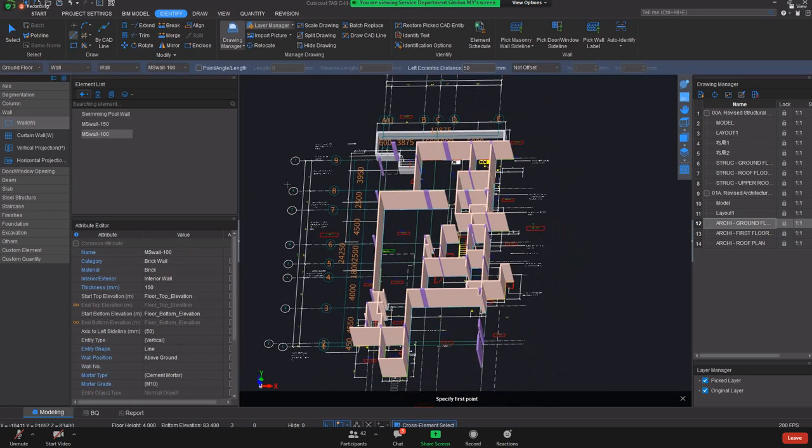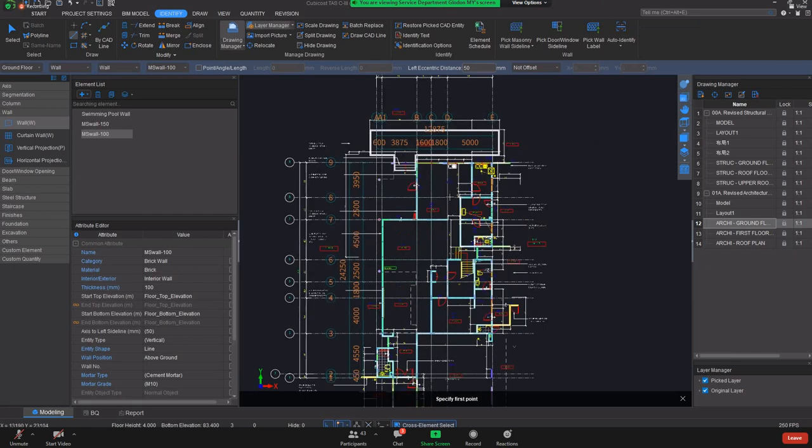But for this auto identify method, it actually reads all the walls as internal walls. What we want is to separate them into internal and external walls. Therefore, when we get the quantities for the external wall finishes, we split into internal and external finishes. So how can we do this in order to separate into two?